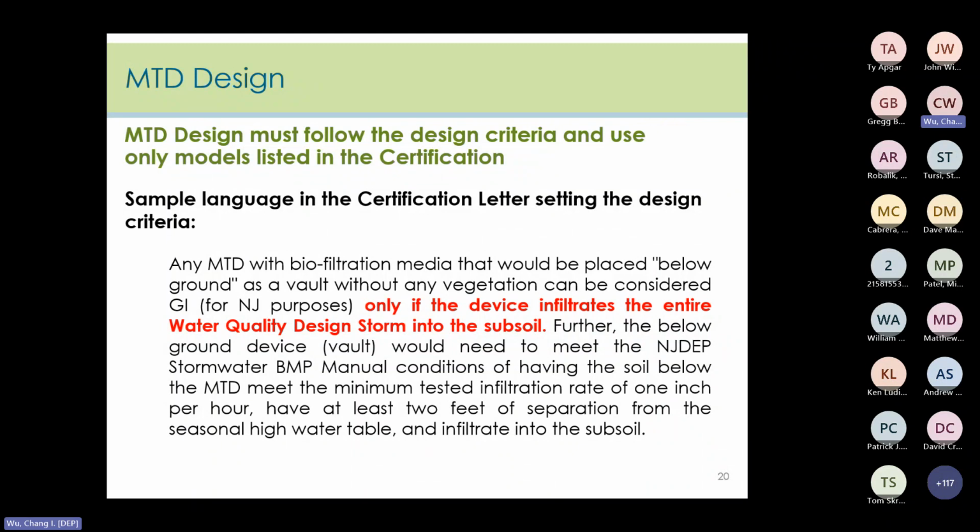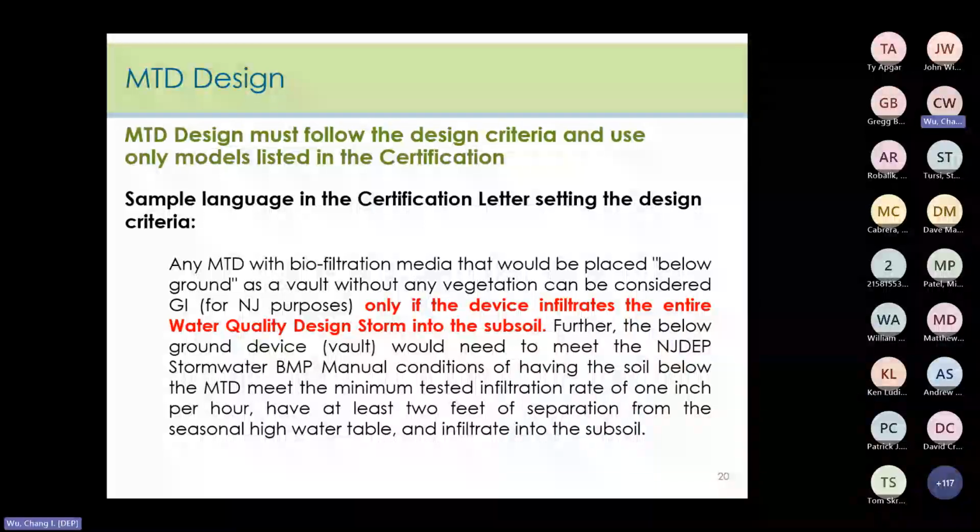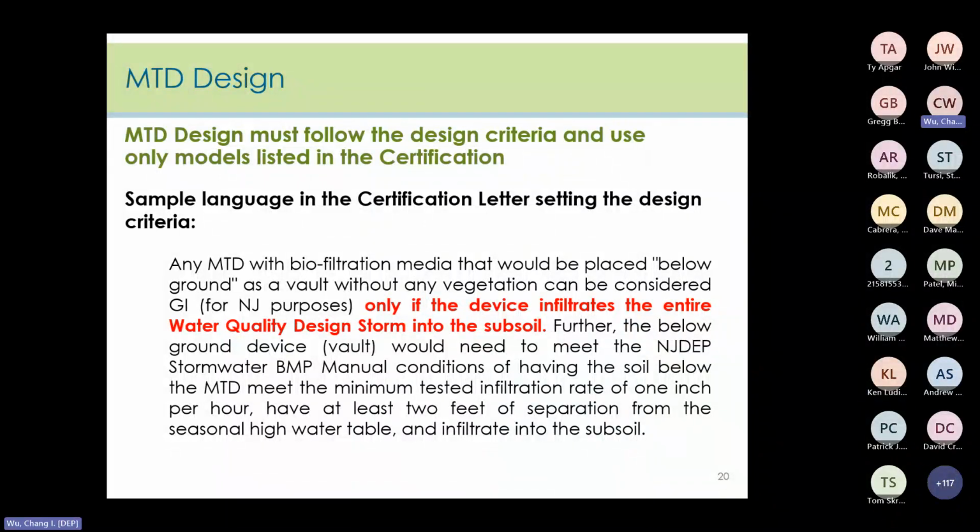And also, that's another emphasis. If the MTD certification says that the GIMTD must infiltrate the runoff into the subsoil in order to qualify as a GIMTD, then you cannot have the MTD installed underground without infiltration of the runoff into the subsoil.